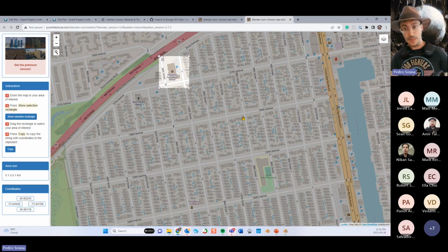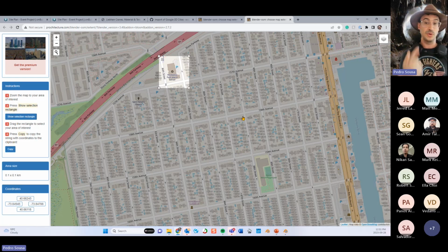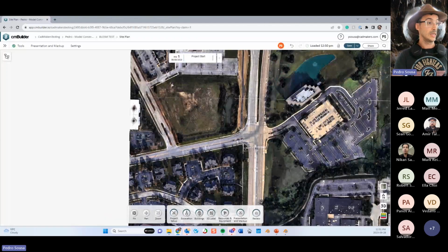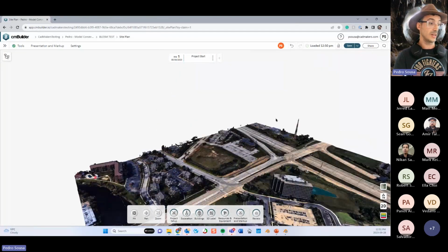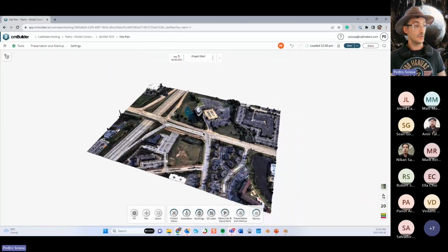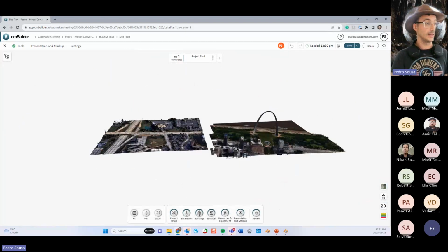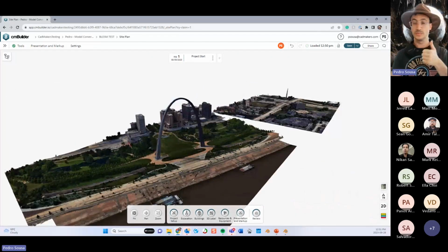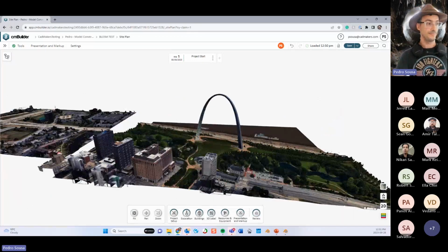So if you keep the browser minimized, and this is not just cmBuilder, this is anything related to 3D view, it's better to keep them minimized because it's just loading and not rendering. So it will load faster. Okay. So for now, if I open this, you can see exactly how it looks once you bring a 3D model into cmBuilder from that Google Maps, the Blender export. See? Does that answer your question, Matt?